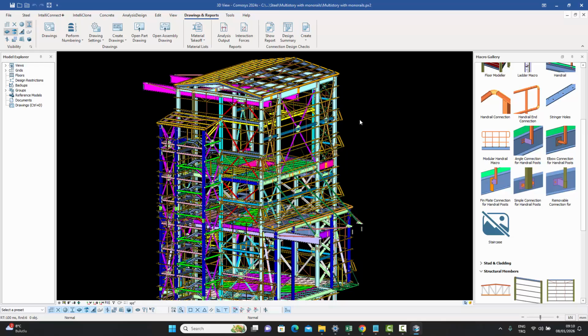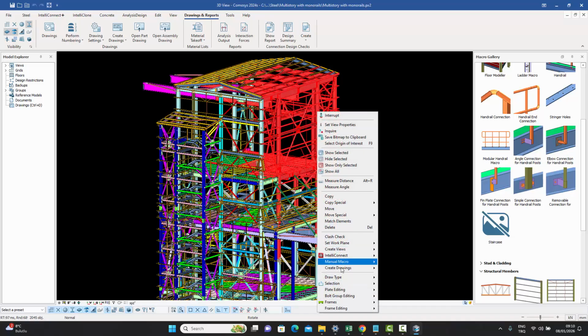The way it works is, normally in previous versions, and that's still possible, you would select some assemblies and parts. You would right click, go to create drawings, and say assembly drawings. We've added this by prefix to tell you that this is the old system in which assembly drawings were created by using the prefixes. But now we have this other option, which is a drawing creation wizard. It's not just related to assembly drawings, it's also related to part drawings. This will allow a lot more flexibility right at the last point, just before creating the drawings.